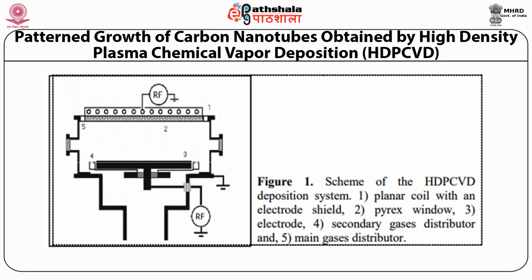In the HDP-CVD system, there are two gas distributors. The main distributor was constructed in the cover of the chamber, where a small homogenizer chamber, a secondary distributor of the gas, exists. The distribution of the gas in the process chamber has been made by a hole ring. The HDP-CVD system has been created to work with 6 different types of gases and 2 different types of liquids at the same time. Thus, it is possible to obtain DLC film with additive nitrogen, fluorine, oxygen, etc.